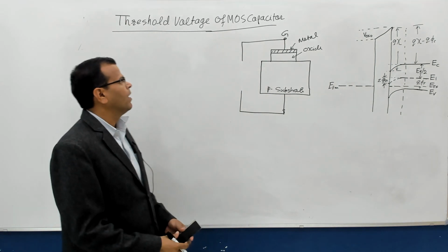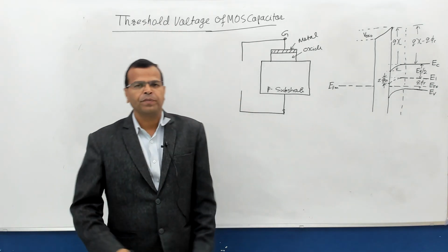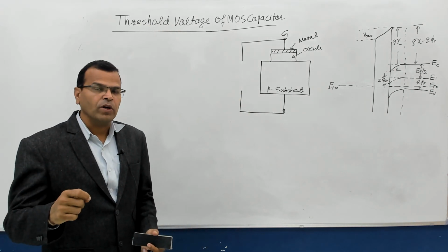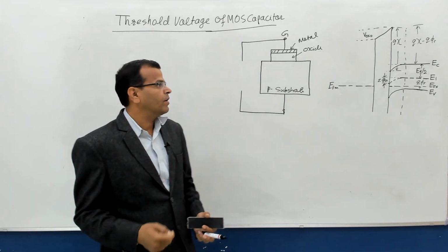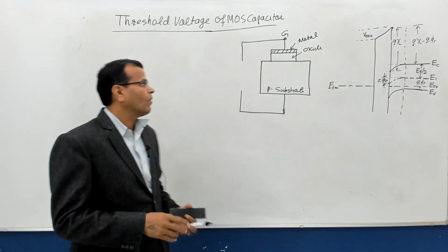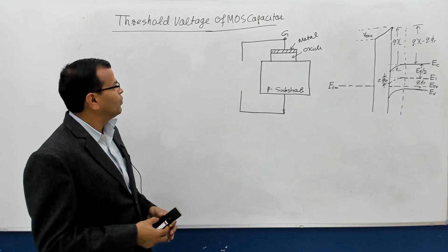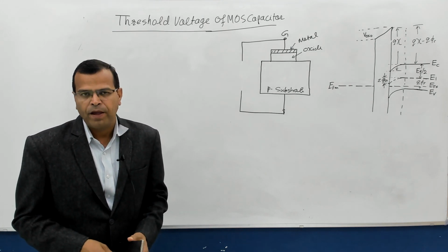Hello friends, the next topic of MOS capacitor is the threshold voltage. Threshold voltage is one of the very important topics of MOS capacitor. There can be a 2-mark numerical in GATE in the coming year itself. Here, before I start with the threshold voltage, I will discuss the flat band voltage.